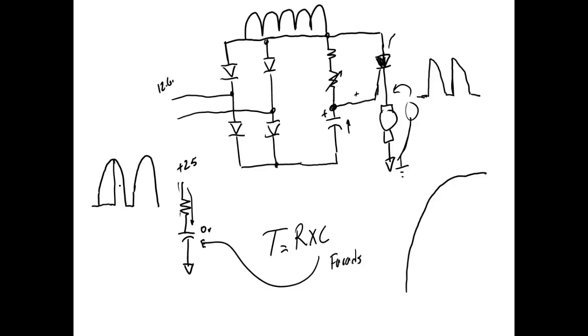Because if I try to set it above 90, the capacitor's not going to charge up there, right? We're going to put too much time in there. So if we're going to use the entire cycle, we would have to use some other type of circuit. But what I wanted you to see is that with these SCRs, I could control a DC motor like this.